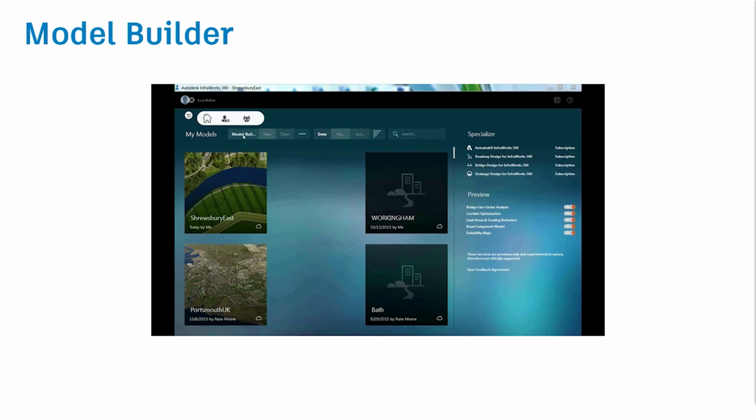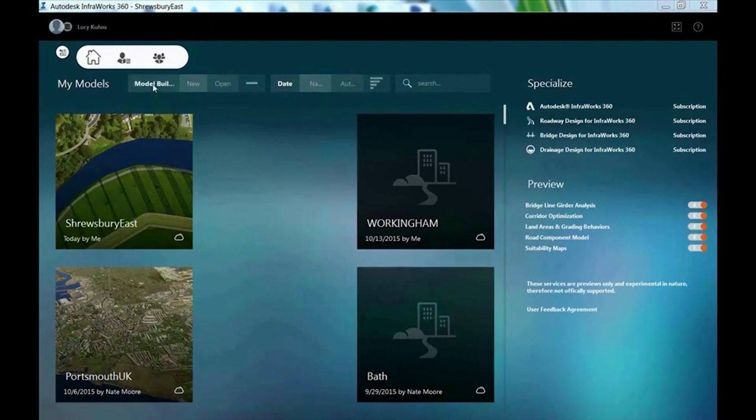So remember, when you get these base maps, that you are at a very early stage of LOD. Okay, LOD 0.5 or something, okay? So, but it's a great way to get started. And then with the sketching tools that we can use, instead of sketching on a napkin or on a map, you're going to sketch in real world context.